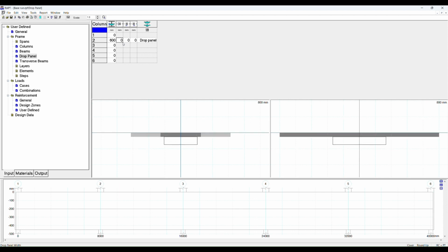Now it's a bit unusual here because you wouldn't put a drop panel on a beam, but drop panels are commonly used for flat plates, and this is how you do it. They must normally be 1/6 of the span length into the span in order for them to be counted as a drop panel. So I'll show you what I mean.